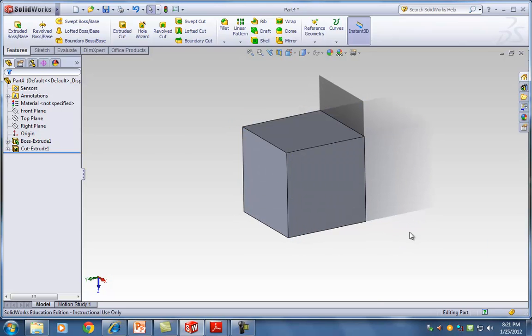So great, you want to mirror. Okay, pick a plane that works for you. Would the front work? Would the top work? Would the right work? You're an offset with mirror? Nope. What would you do? We add a new plane, right?